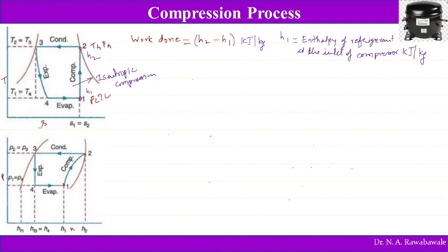So now here enthalpy at point 1, H1, can be obtained if the refrigerant is wet here. It is given by hf plus x hfg, at pressure P equal to the lower pressure PL of this cycle. So at PL, whatsoever is the pressure at point 1, or we call it P1, the properties hf and hfg are taken from the properties of refrigerant table, just like the steam table. So the refrigerant also has its property table. According to that, these values are taken.